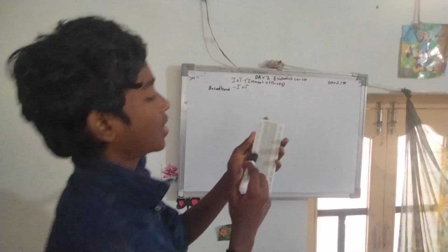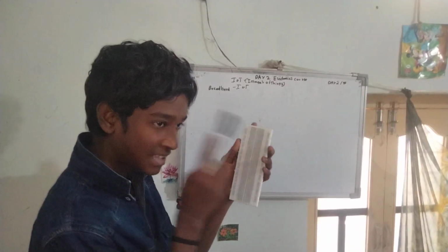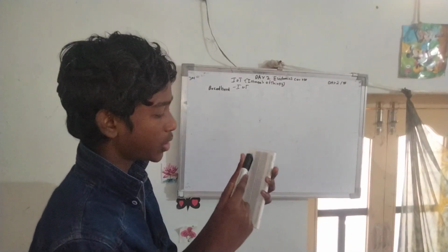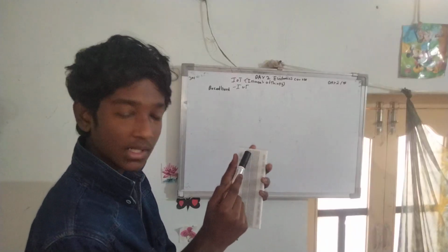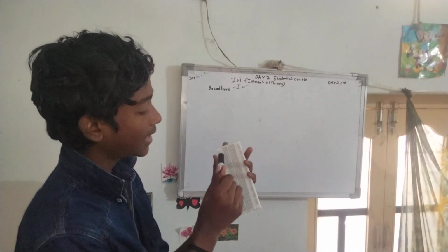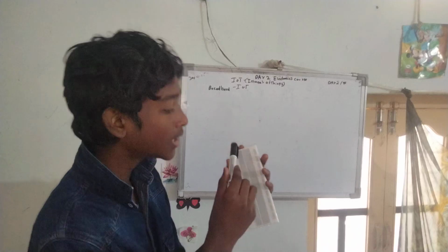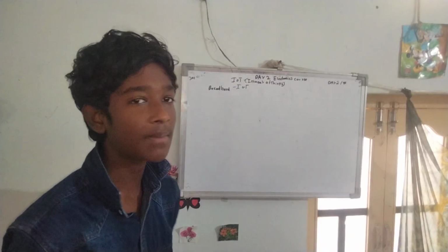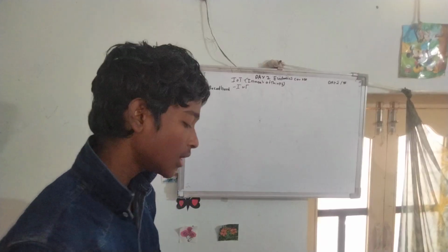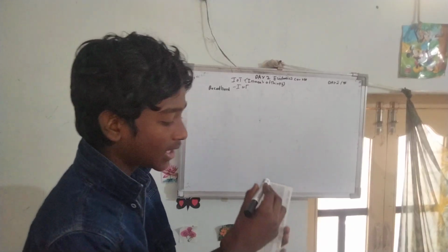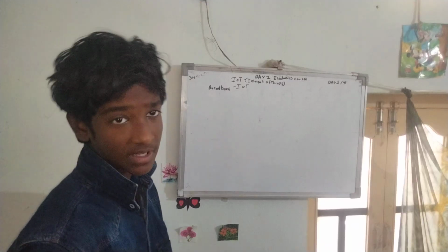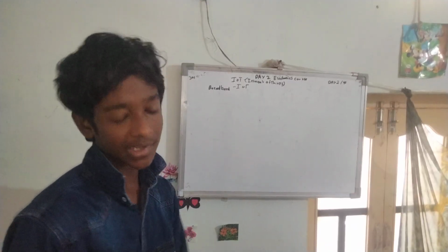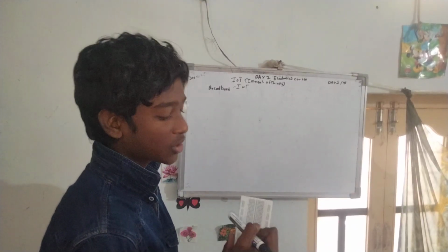So now, whenever we connect a negative, GND or minus point, to this rail, we can get the negative. For example, if we take a battery, we get only one negative point. But if we connect that negative point here, we can get these many points through which we can connect many devices to negative. Same here also, positive.